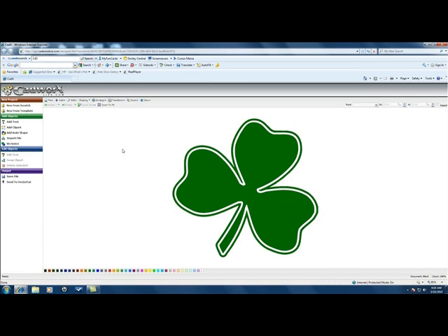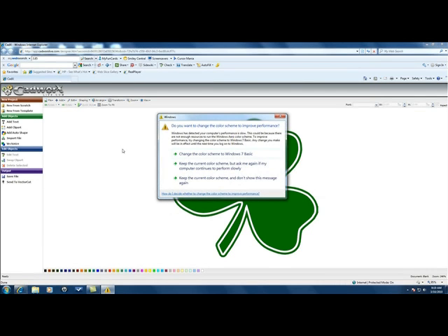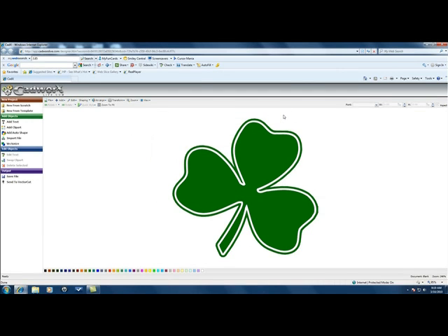Also, when you change the angle of the blade, you also want to change the offset. For example, the Roland GX24 comes with a default blade of 45 degrees, and you'll want to change that. If you're changing to the 60 degree blade, then you want to change the offset to 0.40.